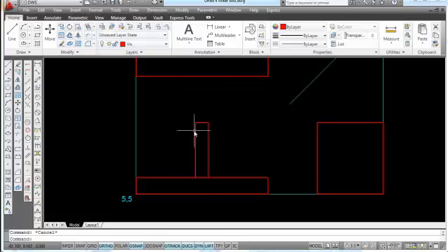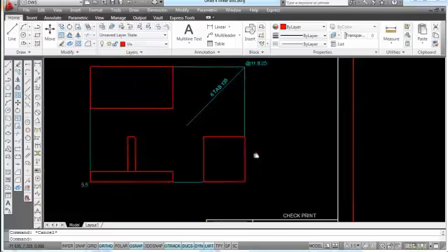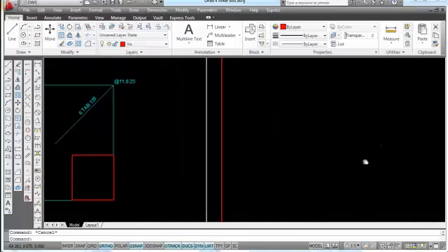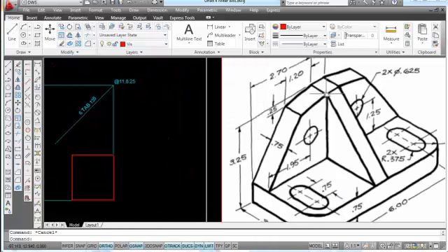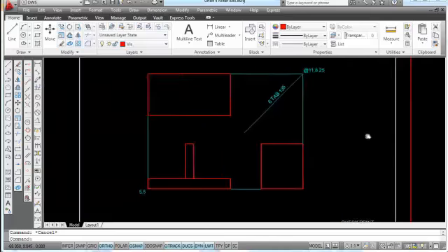The next thing I'm going to do is I need to draw the angled lines that come across here. So I'm going to go back and look at my sketch again. And so at the top of the inclined plane, I have a sloping line that comes over 1.2 inches and down 0.25 inches, and then from there it goes down to this corner. So let's add that. I'm going to draw a line that goes over to negative 1.2 in this direction and then down in a negative 0.25 to get to that point right there.